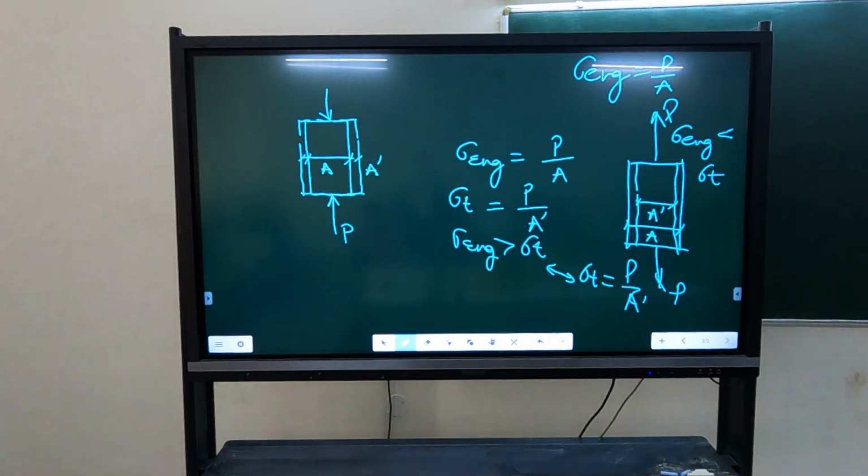That's why when he was asking why we are not multiplying by 0.85 here, we will multiply by 0.85, but later, after taking the effect of confinement on cylinder strength. Because Mander's model has been derived for cylinders. That's why we will first do everything in terms of cylinder strength, and then we will convert into the structural strength by multiplying it by another factor of 0.85.